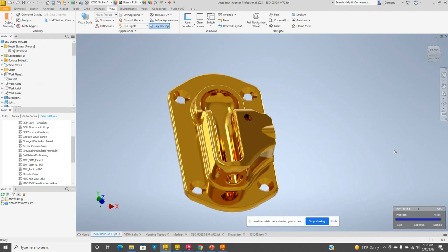If you've used Inventor Studio, that is still using the Autodesk ray tracing, which is called ART. It's basically just Autodesk Ray Tracer. So right now, the model and the part file environment are using the GPU if you set it to that. So you will get, again, better performance, better capabilities. However, not every graphics card is supported.